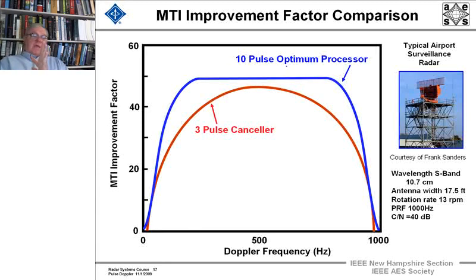That will amplitude modulate those pulses and spread the clutter, so that for each and every Doppler filter, in theory, I calculate what would be the optimum processing filter. And I overlap all, in this case 1,001 filters. This is the envelope of a 10-pulse optimum processor.